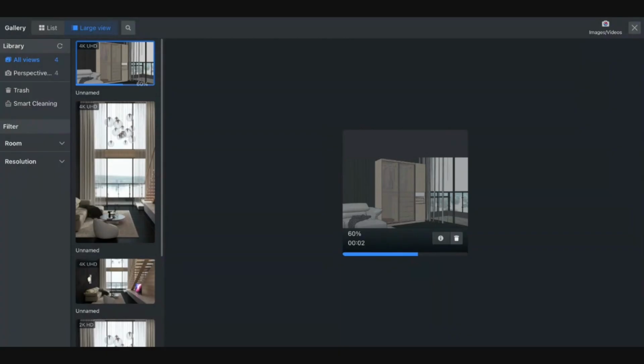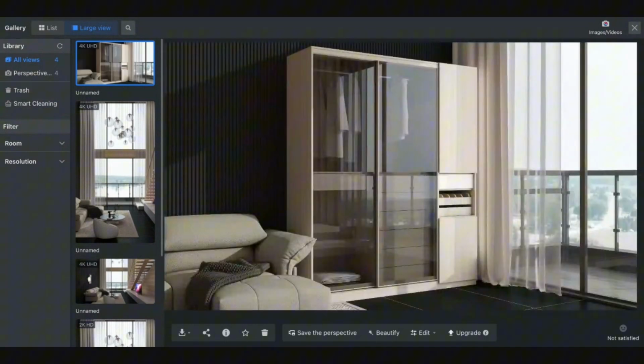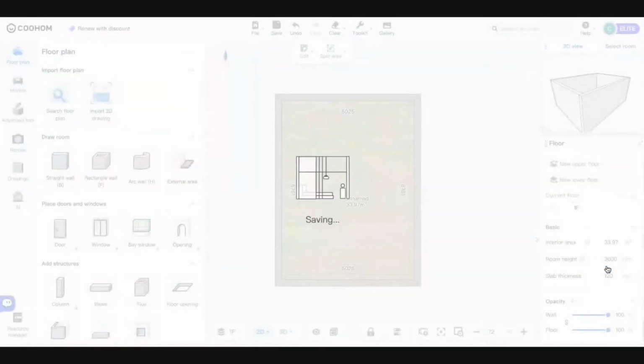And then I first deleted these sections, and then these sections. I mean the wall, the window, and also the doors. And then I just create, as I haven't shared the screen, sorry, this one. So I already changed this floor into 3 meters, and then I create a new upper floor with the same structure. This is another way.